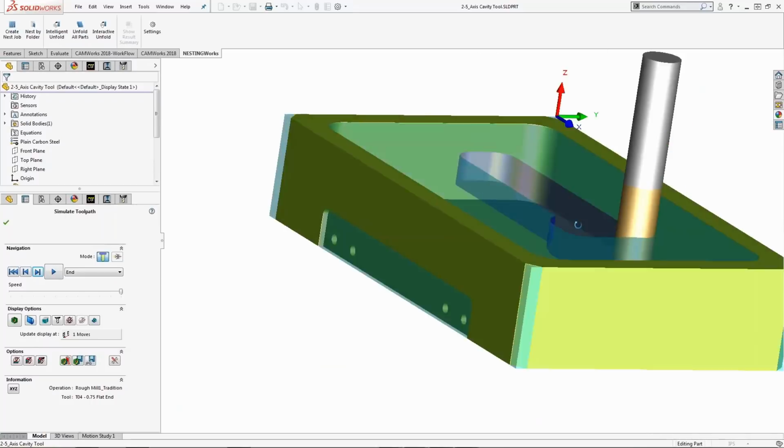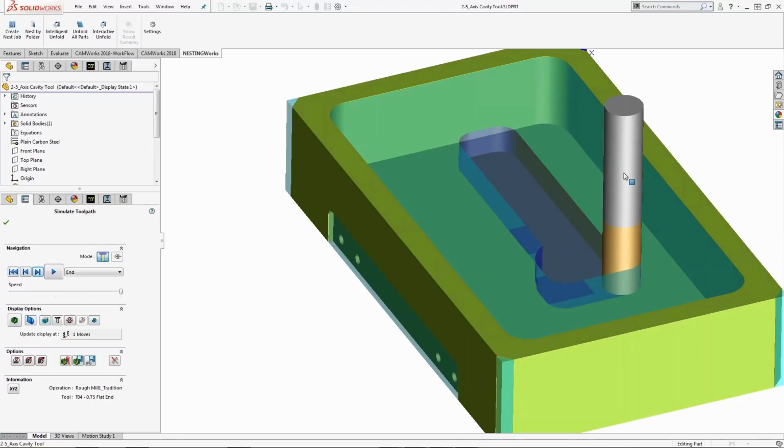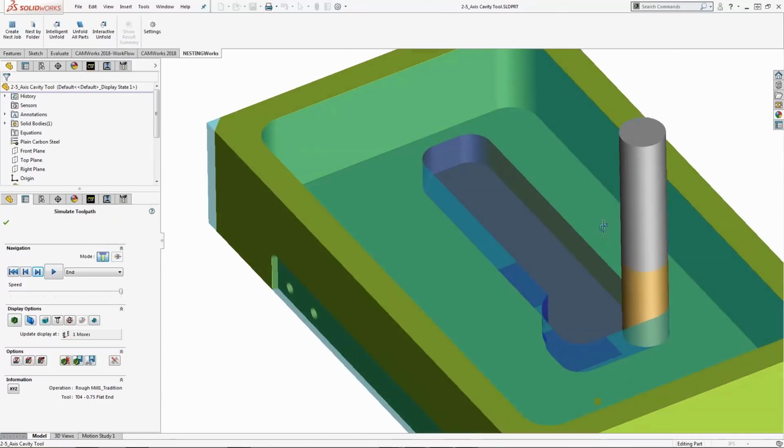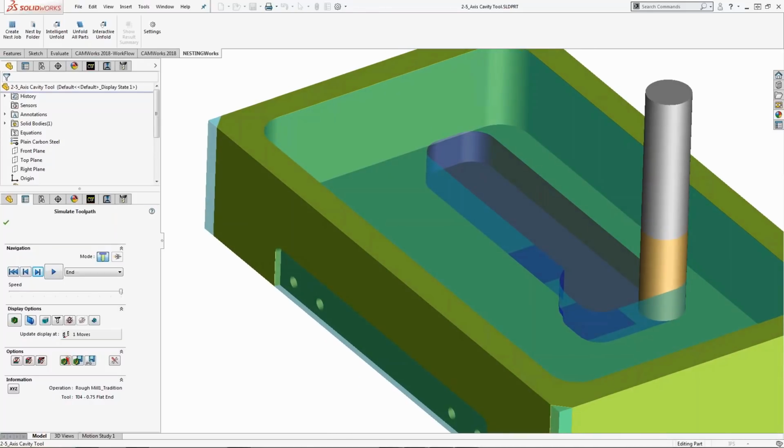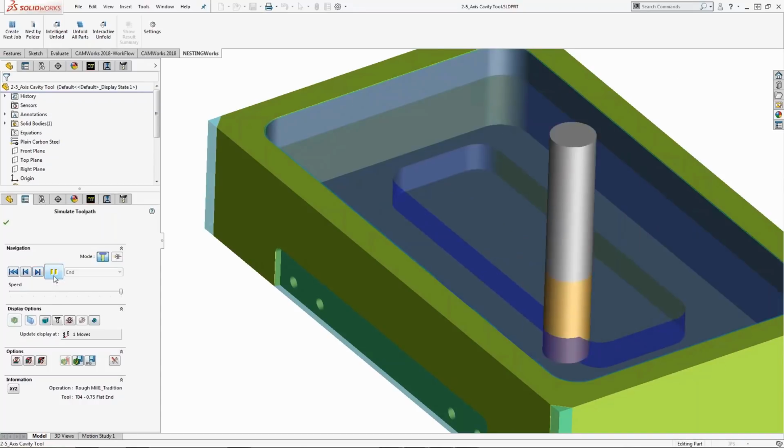If you have a very short tool and a rigid setup, the amount of loading and unloading of the tool, as far as the sound goes, is not going to be too drastic. But if you have a fairly long tool, maybe an extended reach, you're going to get a lot of excessive chatter. Okay, I'll just go ahead and run this out here.